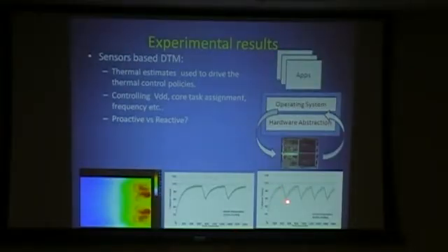So you are measuring sensors, and the temperature is increasing like this. And when you reach this point, the sensor, because it is an inaccurate version of the actual temperature, overpredicts. So it tells you that you have reached your thermal constraint, you better shut down. But because that's an inaccurate decision, you end up shutting down too much, and that hurts performance.